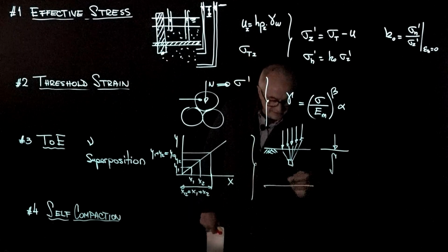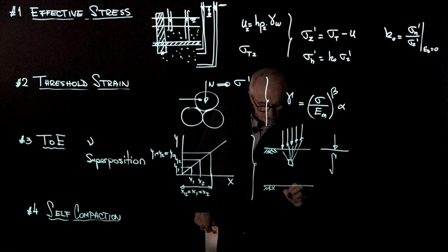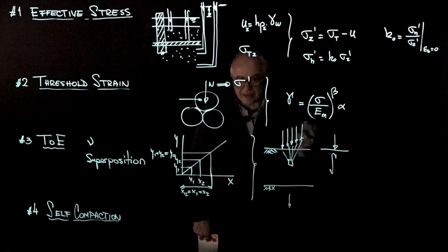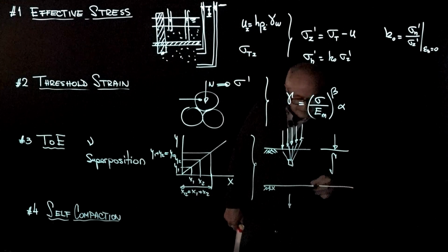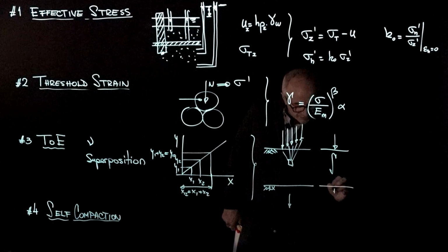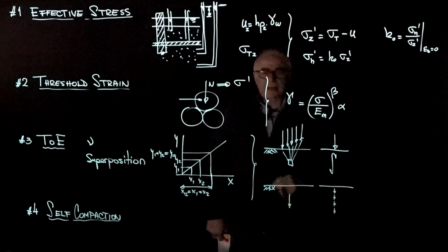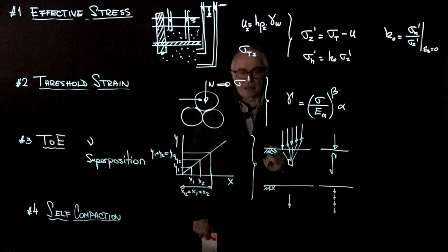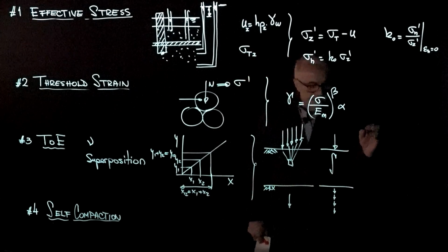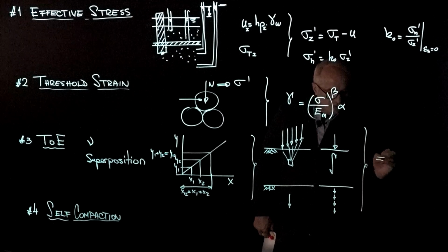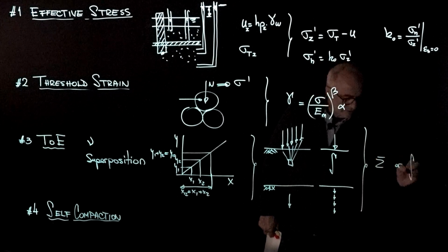Similarly, for example, this is the subsurface now. I have a solution for a point load in the middle of a half space. That's called the Mindlin solution. And now I can integrate it, and I can say what happens if I put a little load at that depth, a little load at that depth, etc. And now I have the solution for the deformation that a pile experiences with depth by superposition of Mindlin solutions. Sum of the causes, sum of the effects means the superposition or integration.